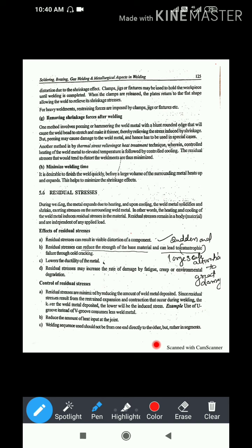See, if you are welding from left to right, you keep going in the same direction. The electrode rod should not move back from right to left. For the overpass, if you are passing the electrode rod once again, you should not pass it from right to left. If you went from left to right, then the next pass must also go left to right.